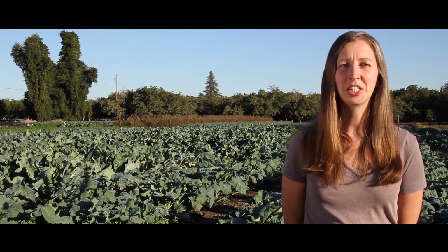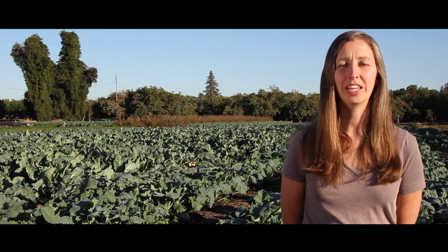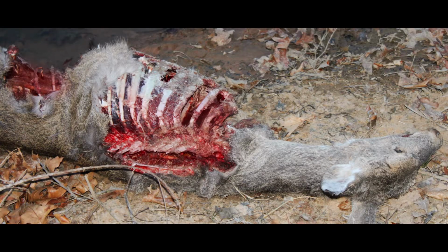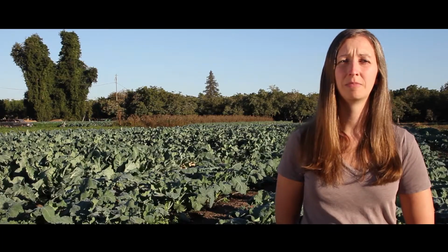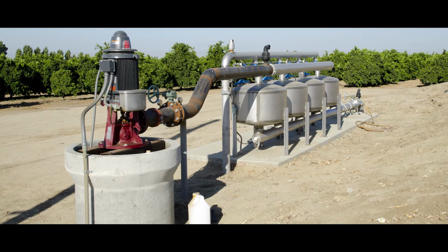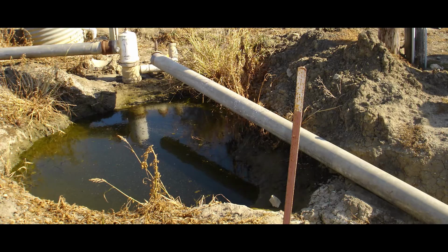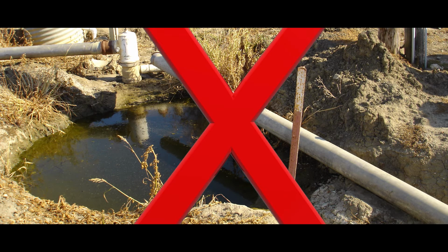System maintenance. By doing routine maintenance on your irrigation system, you can make sure that inappropriate materials such as plant matter, trash, and animal carcasses are not contaminating your water sources. Filtration and disinfection systems also minimize the risk of contamination. Well heads should be free from cracks in the concrete. Wells should be designed to prevent contamination, and closed wells should be sealed and protected.